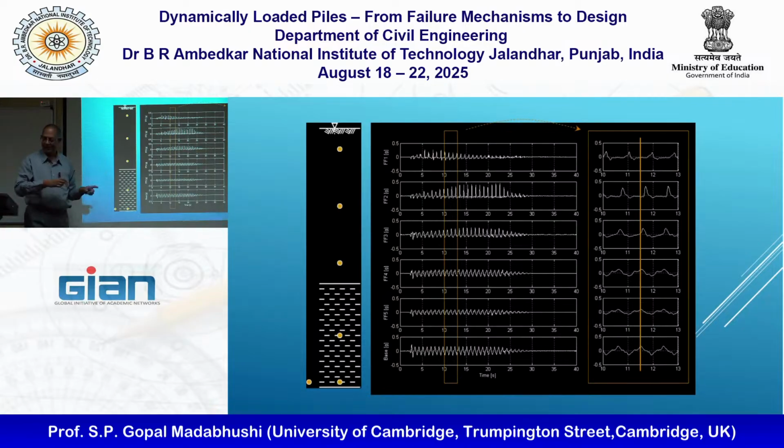This phenomenon was named by Bruce Kutter and I think a guy called Gudgeon as deliquefaction shocks. It's basically a shock wave going through the soil because the soil, which is like liquefied for a fraction of a second, turns into very stiff material and then it softens again. So whenever it is turning into stiff material, it can carry this shock wave. So the physical data you get actually has a lot of meaning associated. And the same thing happens, I'm sure, in reality as well.